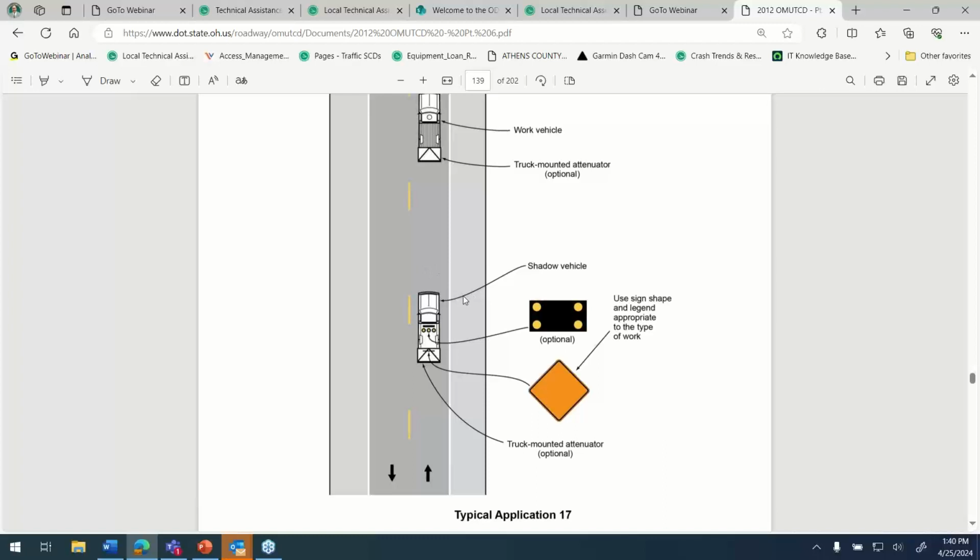Okay, so in this picture we see a 2-lane road, and let's look at the traffic control on that road. It has yellow dashed lines in the middle. That means something. It could be yellow dashed lines, or it could be a double yellow line. The fact that it has dashed yellow lines means that passing is permitted.